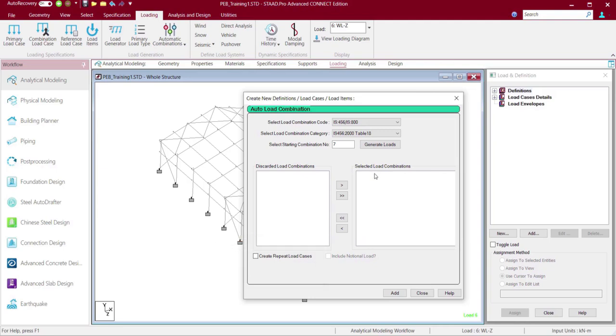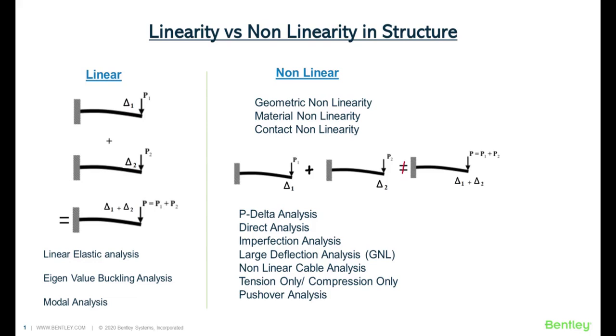Before I go further, let's explain what exactly a repeat load is. Repeat load is a similar combination feature, just like the conventional load combination. The conventional load combination is not going to perform the analysis for that specific combination case. It will only perform the analysis for the primary cases. For example, a combination case is like 1.5 dead load plus live load or wind load.